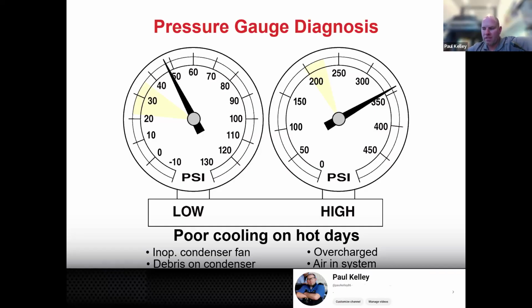Remember on our compressors, we have that pressure relief valve. That moisture and air in the system may actually kick that pressure relief valve. That'd be like a pop off. And when it does, it's not just air that's going to come out. Actual refrigerant, oil, and dye, maybe if we have dye, is going to come out with the air. And it's going to do that until enough of the air gets out that it no longer goes psh.